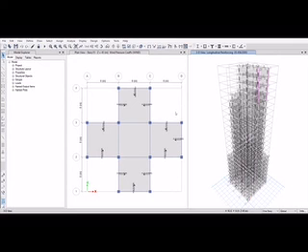This time after the completion of running design, the 3D view displays the longitudinal reinforcement. You can check by going to design, concrete frame design and select verify all the members first. One concrete member is failed, so design check, do you want to select them?